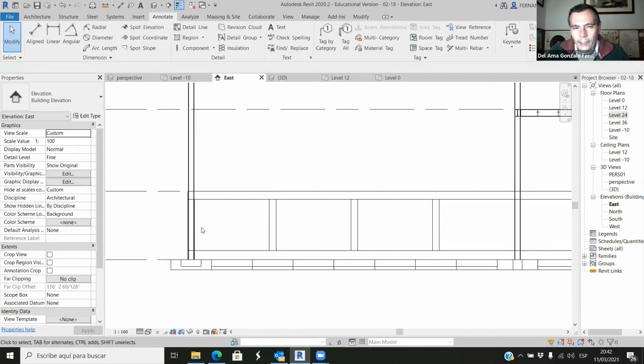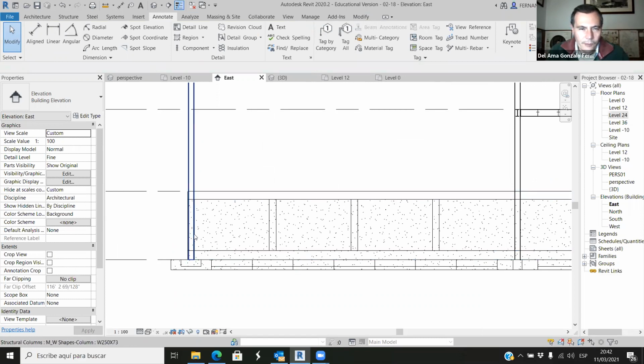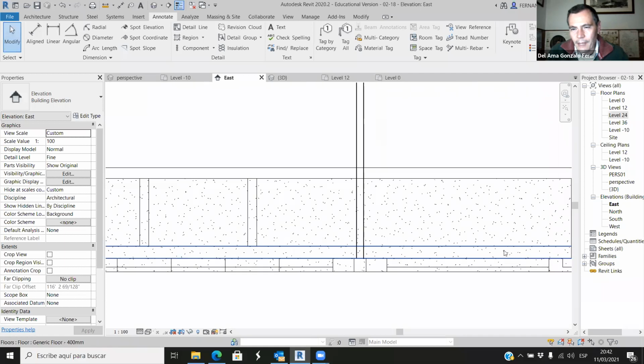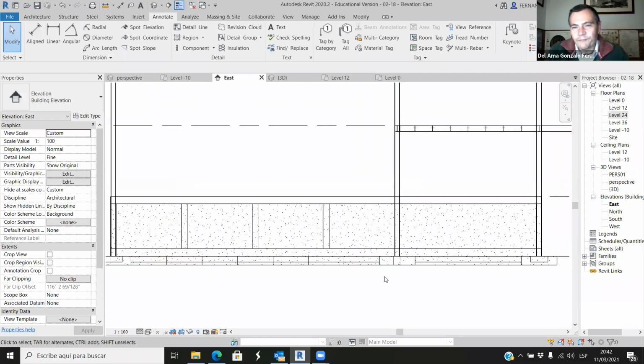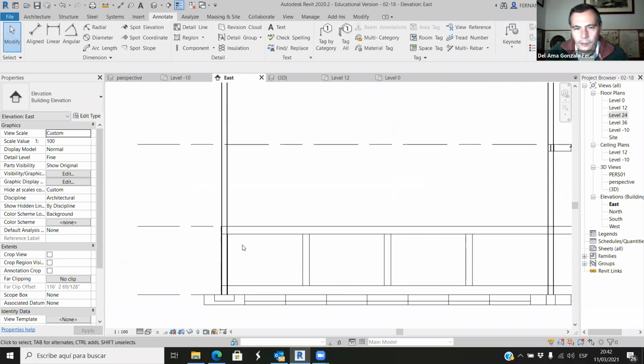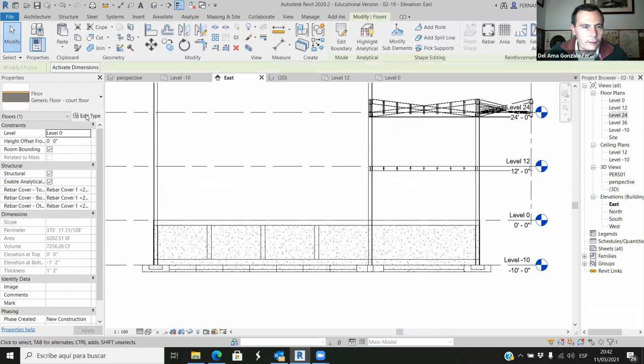Or we can place the thermal insulation in this retaining wall, and we can place the thermal insulation underneath that slab or on that slab. Either way works. Since we have a lot of height here, I think we can place thermal insulation on that wall.